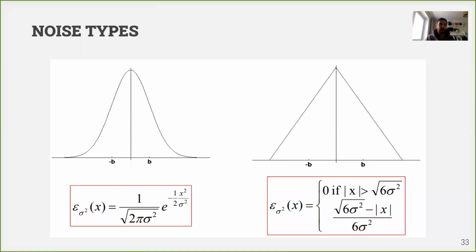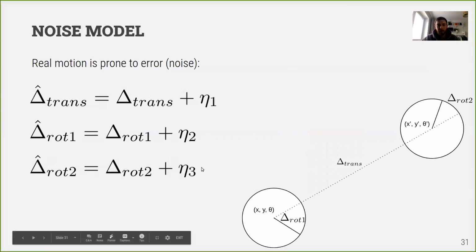And vice versa. If our motors are really cheap and noisy and our world isn't perfect, we have some complex environment, then our variance should be bigger to account for these noises, to make our prediction of where our robot ended up. And then variance will be huge, and still the mean will be 1 meter, because encoders are saying that we traveled 1 meter, but variance will be quite big. And as a result, we will get not a single answer on robot pose. We will predict the whole probability density function of our robot pose. And the same with angles, basically with rotations.